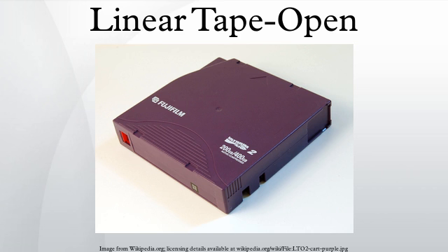Labels. The LTO cartridge label uses the barcode symbology of USS-39. A description and definition is available from the Automatic Identification Manufacturers Uniform Symbology Specification and the ANSI MH10.8M-1993 ANSI Barcode Specification. Erasing. The magnetic servo tracks on the tape are factory encoded. Using a bulk eraser will erase the servo tracks along with the data tracks, rendering the cartridge unusable. Mechanisms. Current compliance-verified licensed manufacturers of LTO technology mechanisms are IBM, Hewlett-Packard, Quantum, and Tandberg Storage.